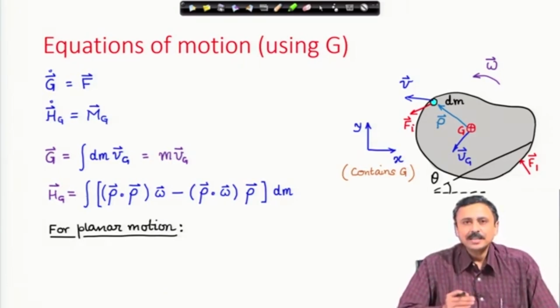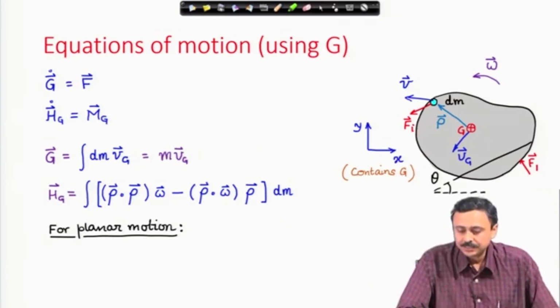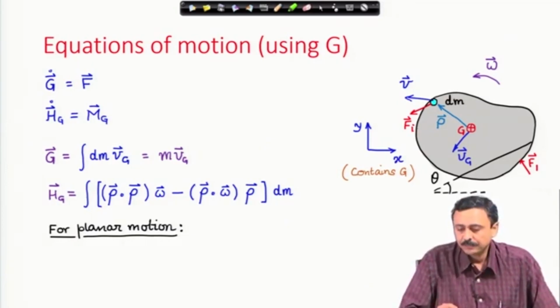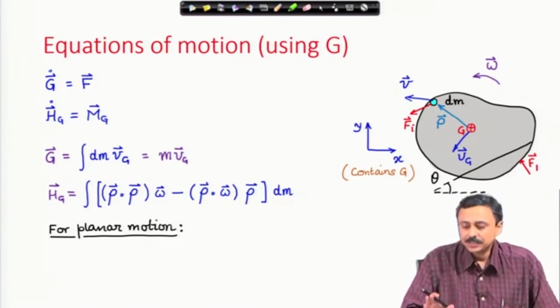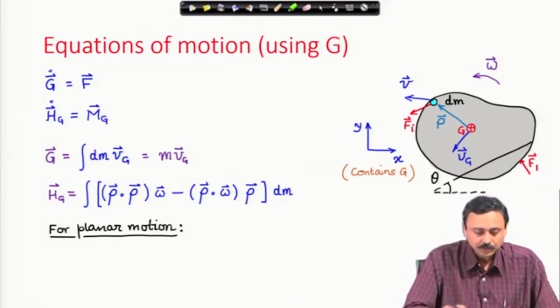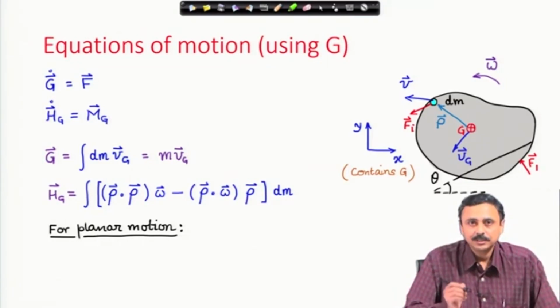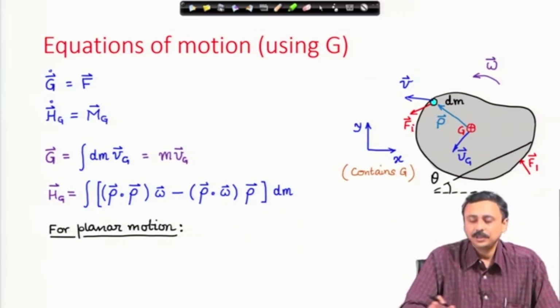Now, let us specialize this for planar motion. I have considered this xy frame as shown in the figure. Here there is a point to be noted very carefully. The center of mass of the body must lie in this xy plane. We are going to consider planar motion. The requirement for planar motion is that all points of this rigid body must move in this xy plane.